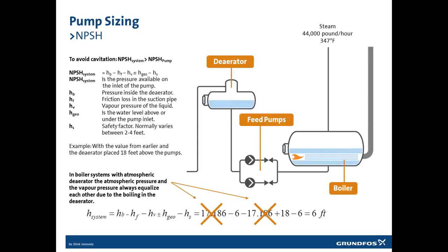Yes. And then there was one additional question. Do we calculate pump for operation parameters or max demand? I think that's referring to the pump sizing. Shall we select the pump for the normal operating parameters, or do we select the pump for max demand? ASME code says that we should size the pump for the boiler data nameplate. That means it has nothing to do with operation. It's the boiler data that we are sizing for.